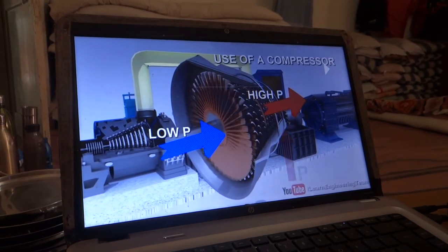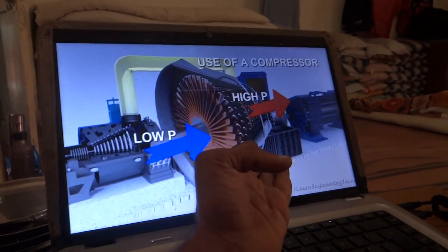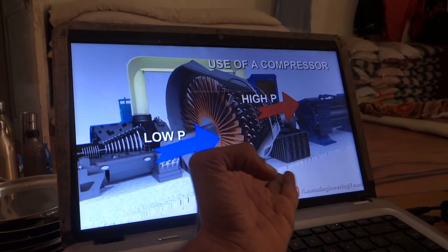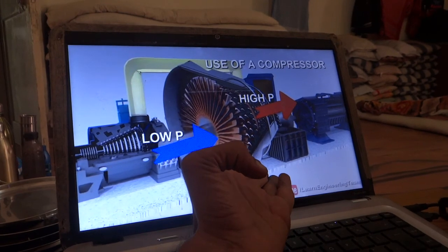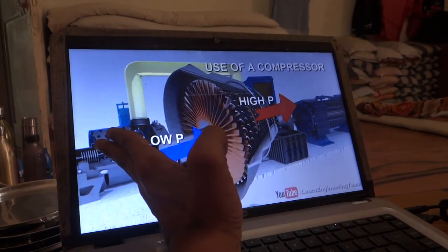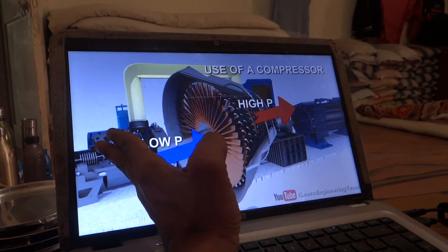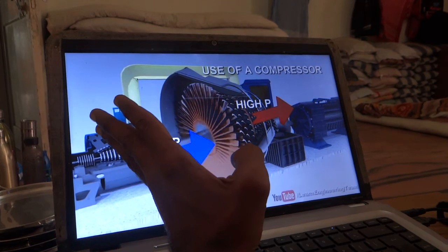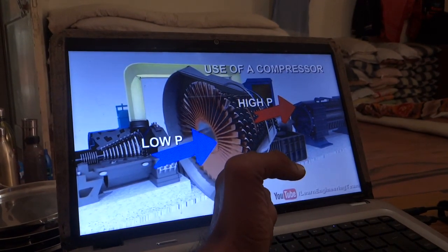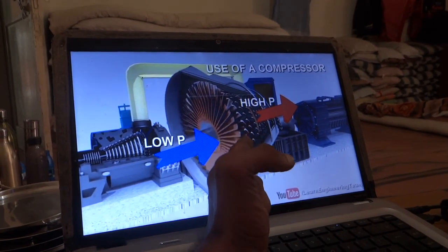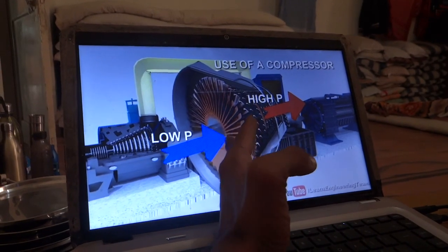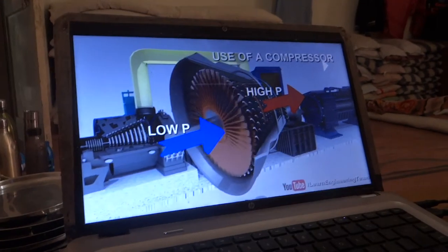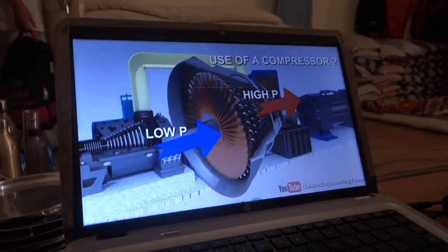So, yes. There was such a point: the steam which is coming out, why are we condensing that, why are we converting that to water? Can it not be directly fed back, just increase the pressure and temperature of the steam and feed it back? But to increase the pressure and temperature of the steam, you need a compressor, and compressing steam is a big job. The power plant will not be efficient at all, because it takes a high amount of energy.